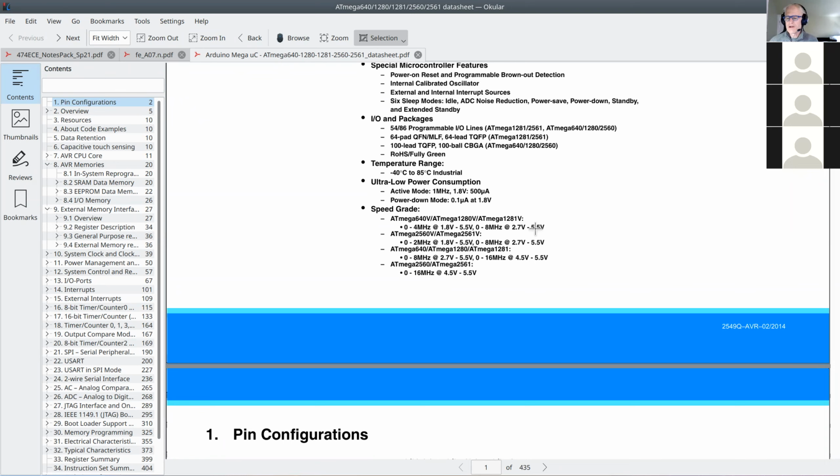The Arduino environment by default turns on all the timers, so they are turned on when we're programming them, but we could play around with turning them off, except for the ones we want to use. I don't do that in the lab that we're going to do with timers because I'm not exactly sure which timers Arduino really needs for its background stuff. So I'm not going to mess with it.